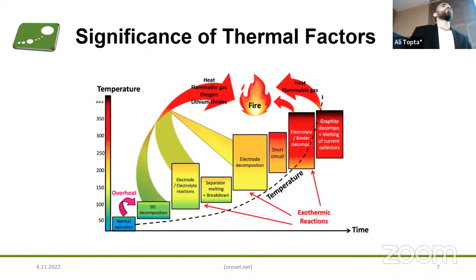I've said that we have used sodium alginate mainly for the flame retardant property, and it's very important in batteries, because whenever a battery is exposed to elevated temperature, our membrane gets melted. Whenever it's melted, the electrodes come in contact with each other, causing a short circuit. Whenever a short circuit is happening, the temperature would increase more, and that means that more volatile components and combustible gases are being released, which eventually leads to an explosion.